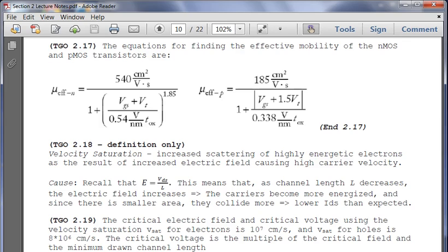Knowing this is important, especially when we get to concepts of logical effort, buffering, and simulation. Knowing how it works at the transistor level when you're putting transistors together will allow you to more effectively take these cells that we're going to be building and ensure there's proper operation. It's not just enough to put the gates there. You have to make sure the gates work together, and then you have to worry about the wires being able to carry a proper amount of current at the output and so forth. So all of this builds up.